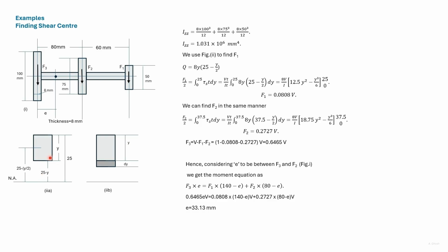So for this portion, the statical moment is given as 8Y(25 minus Y by 2), where 8 is the thickness. The statical moment is area into distance.